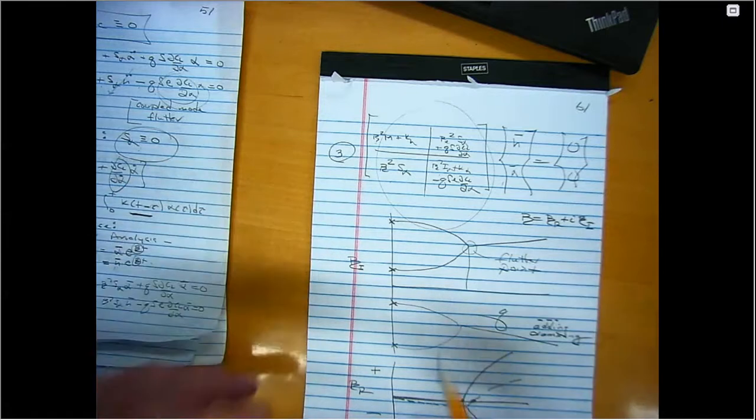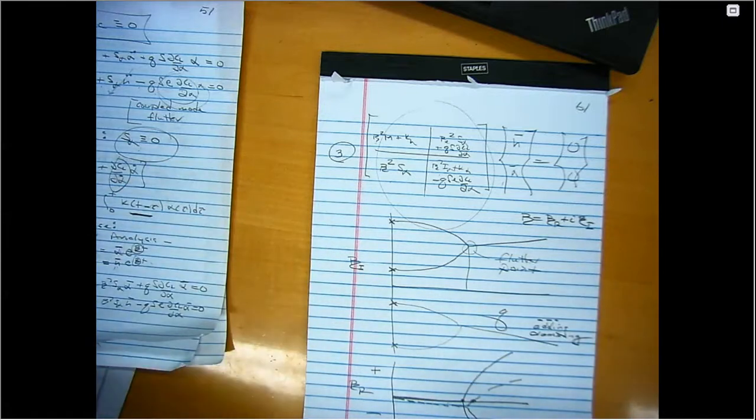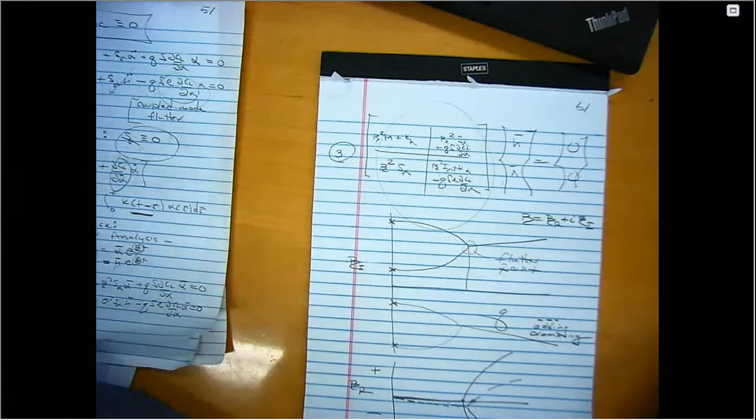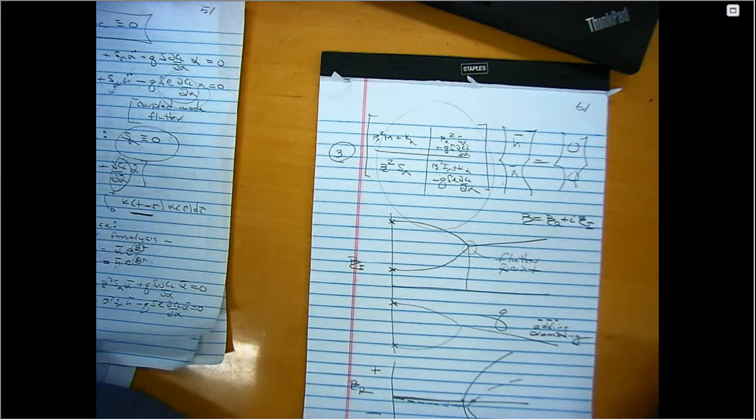And it has to do with the fact that I'm dealing with 2 coupled modes. So I may have added positive damping to one mode, but since they're interacting, that energy associated with positive damping in one mode can lead to an unstable system in the coupled mode system. And that can happen, by the way, with structural damping models, as well as aerodynamic damping models.